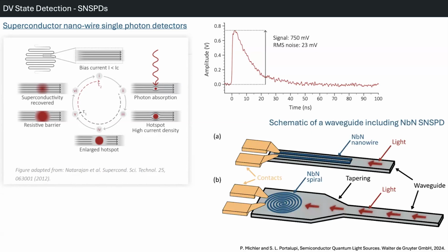And the thing is, you need nanowires from superconductors, so you have to implement your fabrication process. Like with silicon photodiodes, you produce several hundreds of them, and you only pick a few of them, because the distance between these superconducting wires and their dimensions determine which wavelength you can detect with this technology. It doesn't detect all the wavelengths together.